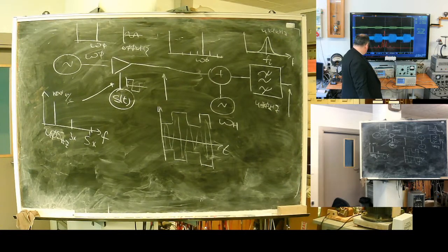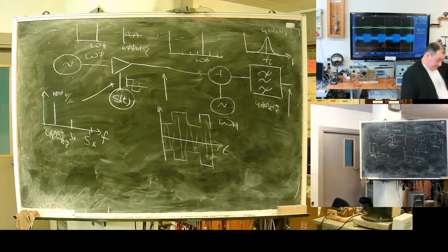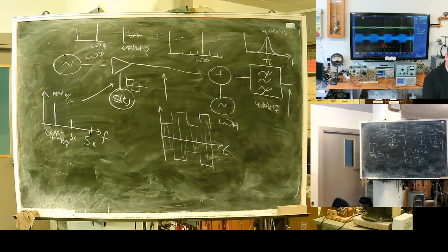The idea with the mirror channel is that there are two differences. See what's the problem. In my case, the heterodyne frequency was above the signal frequency, and I have a result on a frequency of the difference. But there is another signal possible. In my case, heterodyne was above signal, but there is a signal above heterodyne with the same difference, and it will form a mirror channel.